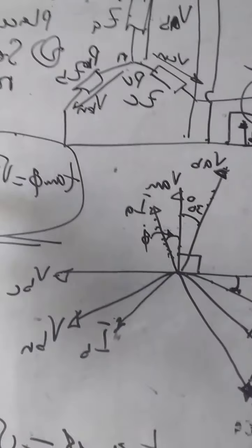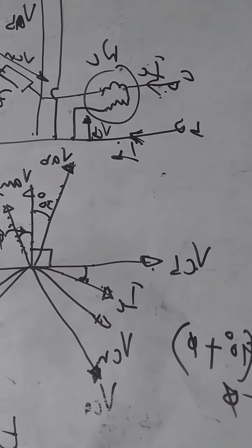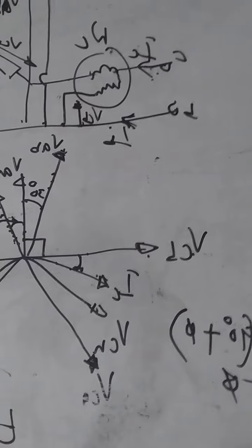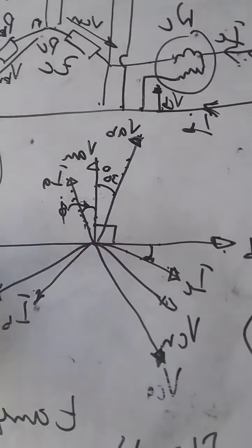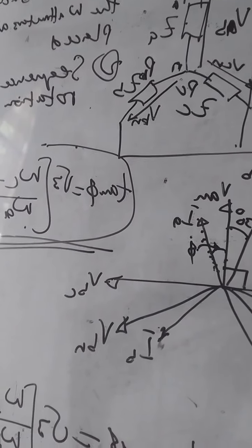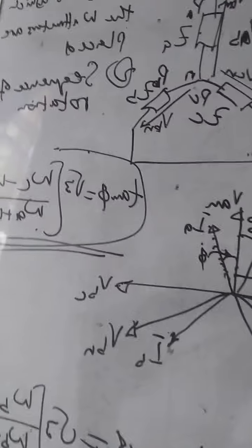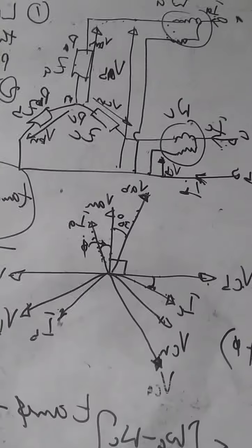So, for example, let's take this one. If it is on C and A, it will be tan phi is equal to root 3 into WA minus WC. The denominator stays the same, WA plus WC. Right. So those are the formulas that we are going to use to obtain the power factor.